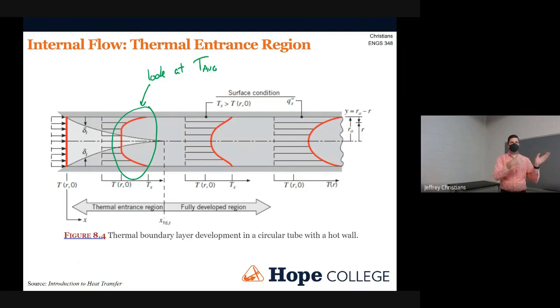Because then we're going to do other stuff and maybe it's all going to get mixed together and turn out 8 degrees. That's what we want. We don't care if the center is 7.5 and a little ways away from the center is 9, as long as the average is 8. Right. So we're going to approximate these temperature distributions at every point as just a flat average, and neglect the fact that there are actually temperature distributions there. We're not totally wiping away all of the temperature distributions, because those temperature distributions are what give us H. We're just neglecting those temperature differences in terms of how we're looking at it heating up.